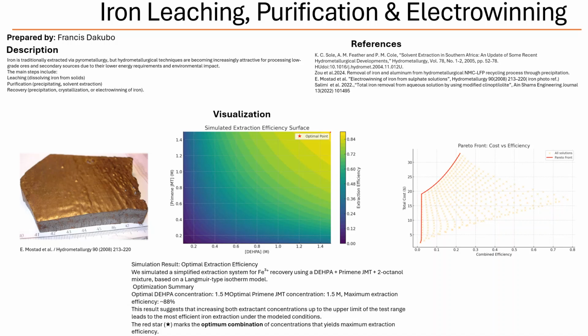Meanwhile, at the anode, sulfate ions are oxidized, which regenerates sulfuric acid, and you get oxygen gas as a byproduct. Plus, some ferrous iron gets oxidized back to ferric. So the diaphragm prevents those products from the anode from messing with the cathode reaction. Exactly. You don't want oxygen gas or ferric iron near the cathode. They'll interfere with the iron deposition and reduce the efficiency. The diaphragm acts as a barrier, ensuring that the iron deposition process can run smoothly.